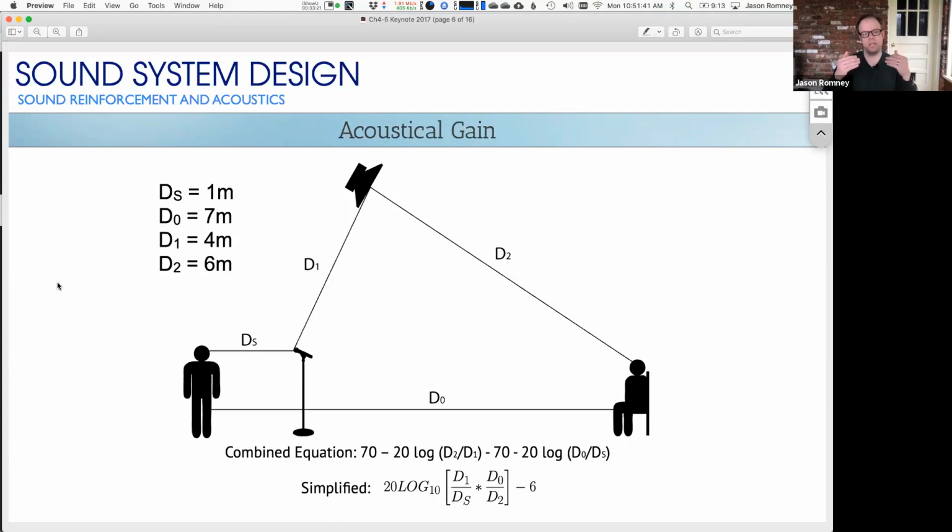Other strategies, for example, could be: never let the sound of the mic go through a loudspeaker that is pointing at the mic. So if you've got a monitor loudspeaker that's coming up from overhead on stage or maybe from the sides, you should probably not put the voices through that because those voices are going to hit the mic and you'll get feedback. So it's actually pretty common, particularly in musical theater where you're using these omnidirectional microphones, to just not do vocal foldback, vocal monitoring.